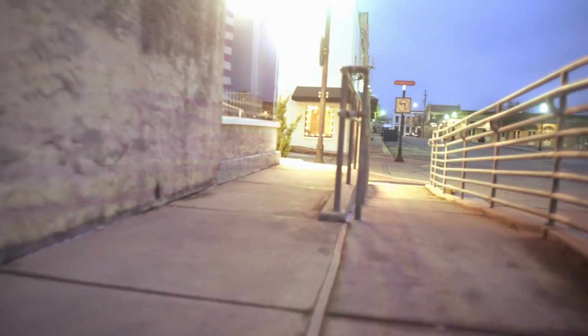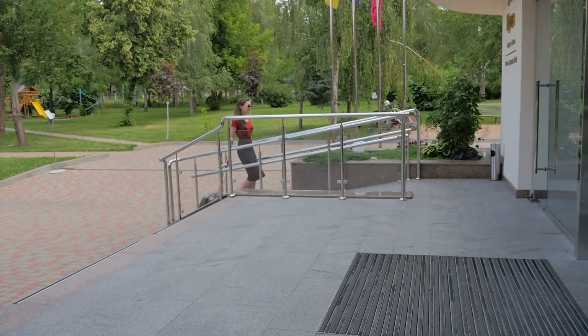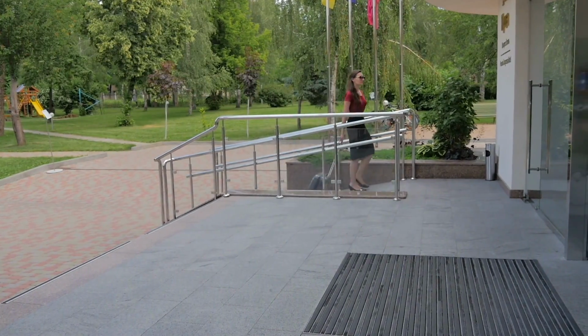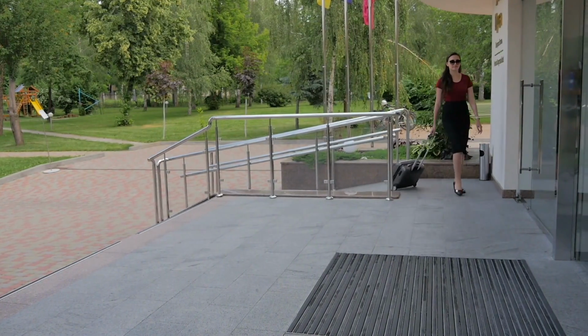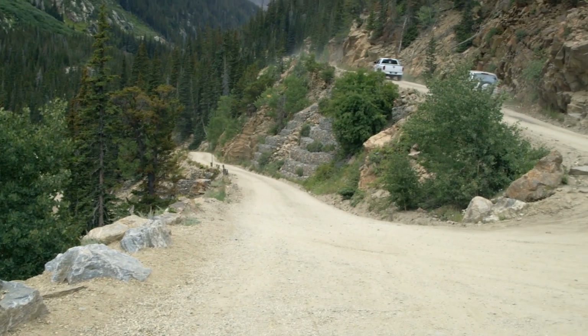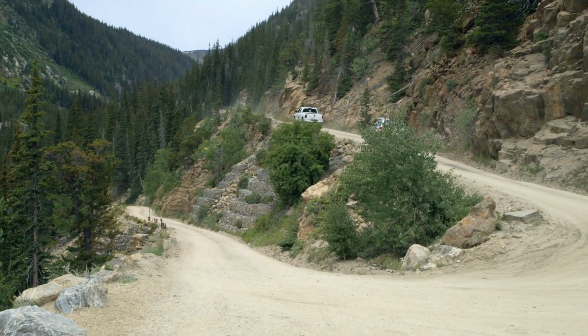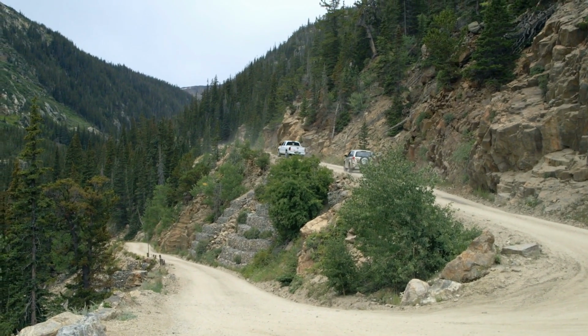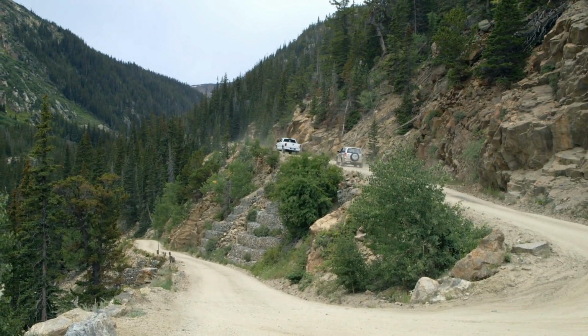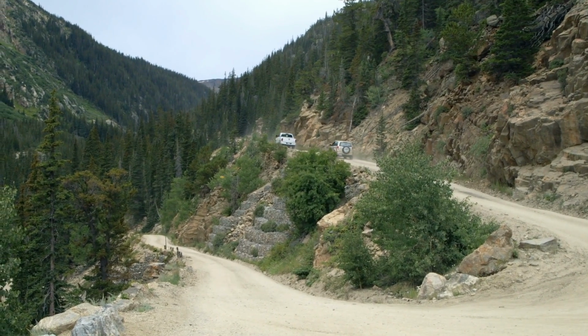The inclined plane consists of a sloping surface and is used for raising heavy bodies. The plane offers mechanical advantage in that the force required to move the object up the plane is less than the weight being raised. The principle of the inclined plane is used widely, for example in ramps and switchback roads, where a small force acting for a long distance and slope can do a large amount of work.